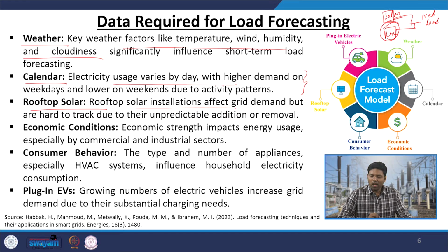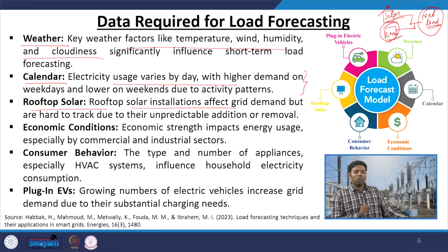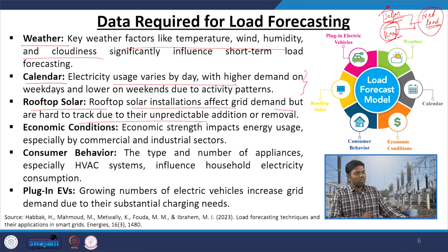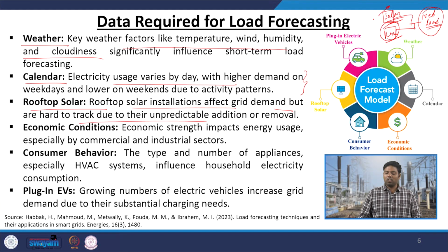Okay, you are just seeing the net load, but that is not your actual demand, right? If some days this solar goes out of order, at that time you will ask for your total demand. So, first you have to know how much solar power generation there is and how much masking is happening with your total demand. So, your rooftop solar power generation needs to be tracked to track your load, because it is unpredictable power generation you have at your rooftop.